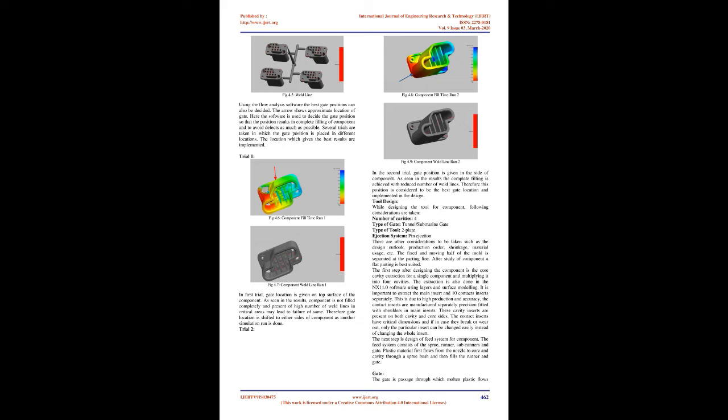Mold flow analysis. Mold flow analysis is a simulation for the flow of plastic material which helps to evaluate the part, parameters, and mold design to produce good quality parts. The analysis can give results such as fill time, cooling time, flow pressure, etc., and can indicate defects such as location of weld lines, air traps, short shot, burn marks, etc.